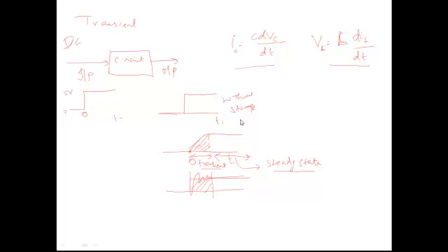remaining circuit. This is because, please understand, I told you inductance will store energy in magnetic field. Therefore, when inductance is coming into the picture, you are always working with the current through the inductance. I already told you current through the inductance will not change instantaneously.